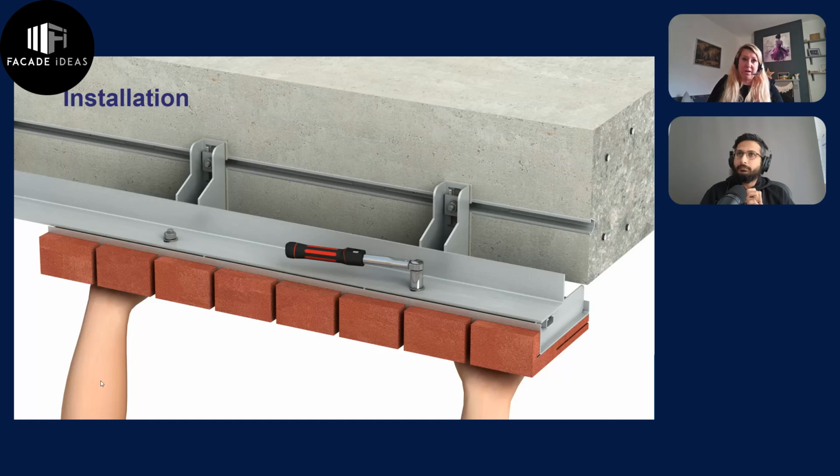The trays that we design are typically just under 900 millimeters long, so a fairly lightweight solution as well. They're simply offered up to the masonry support and lined and leveled. This is a really effective way of producing what we would call floating brickwork for long spans of openings.